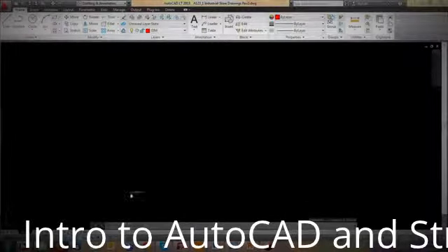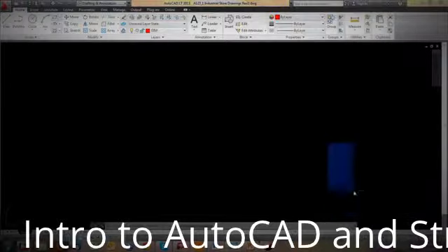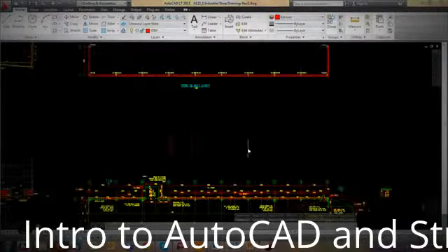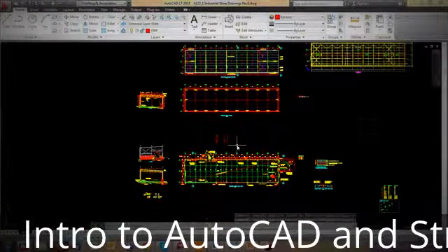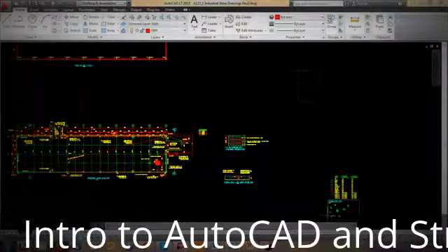We've covered the command line. Then at the bottom we've had a look at the model space, the paper space, and then also there's various tools down the bottom here. Those are for scales, those are for tools. You can adjust scales you're drafting. Be very careful of adjusting scales within model space. I'd encourage you, just for now, for simplicity, draw everything at 1 and 1. Adjust your dimension tools and just get along that way.